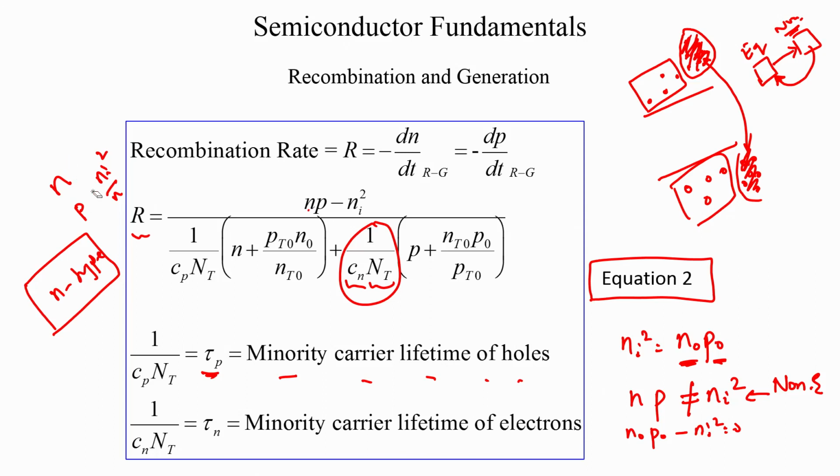Now, you take the semiconductor out of equilibrium and you add some excess holes inside the semiconductor. Now, there are many electrons and you have just injected some extra holes, you have shifted the semiconductor out of equilibrium. Now, the typical time, a measure of the time these holes would last in this n type semiconductor is the minority carrier lifetime of holes.